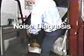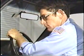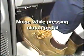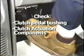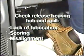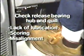In our first topic, noise diagnosis, we're going to focus on when the noise occurs rather than what the noise sounds like. Here's an example of a noise that occurs only while the clutch pedal is being pressed or released. The obvious components to check are the clutch pedal pivot bushing and other clutch actuation components. If you find no problem there, you should also check the input shaft quill that the release bearing slides on. Look for lubrication, scoring, or alignment problems.